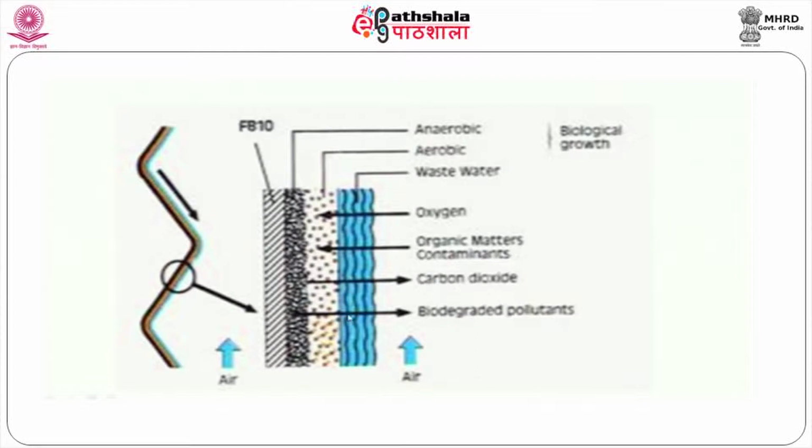So, this is a diagram here. The blue shade represents the water film, the liquid film. This is the biological film. So, whatever organic matter is present in the liquid layer will diffuse into the biological film by diffusion. If any solid particles or polysaccharides are present in the effluent stream, they will be converted into soluble matter by enzyme mediated transformation, because bacteria can absorb organic matter only in soluble state. The insoluble organic matter will be converted into soluble matter by hydrolytic enzymes. So, during enzyme mediated transformation, the polysaccharides are converted into monosaccharides that can easily diffuse into the bacterial cell wall.